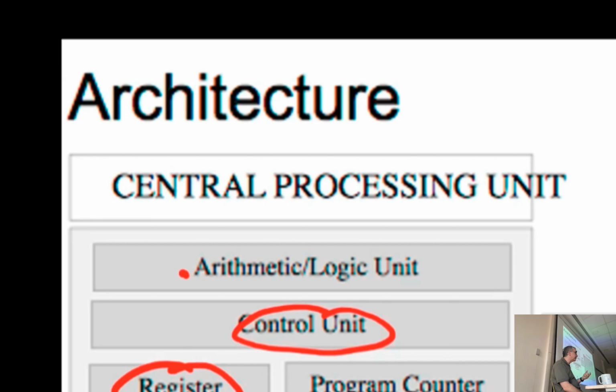So that's the clock. And at each turn, this is increased. This program counter at the beginning shows here. After one turn, it shows here. Another turn, it shows here. Another turn, it shows here. So the program moves at each turn of the clock. And at each turn, this content is taken into the instruction register, understood, and executed one by one.